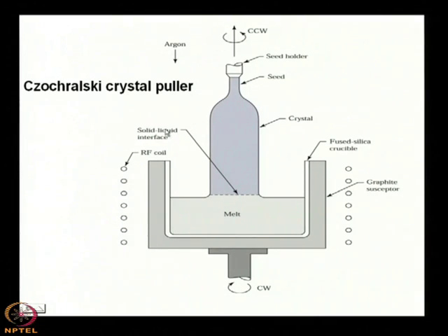That means, this argon will replace oxygen. There is oxygen, so it will replace oxygen, and here there must be an exhaust. Here at the bottom there will be an exhaust through which that argon and SiO gas will be removed. SiO gas will be formed and argon will be there. So, there will be a continuous flow of argon.